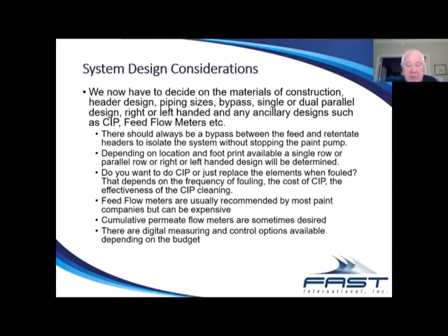Do you want a CIP system or just to replace the elements that are fouled? That will depend greatly on the frequency of fouling, the cost of CIP, and the effectiveness of CIP cleaning. I believe most paint companies out there recommend that a feed flow meter be put onto it, so that you're not just relying upon the differential pressure to be an indicator of the paint velocity.